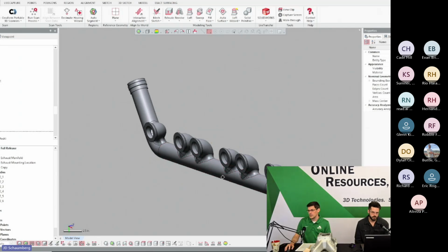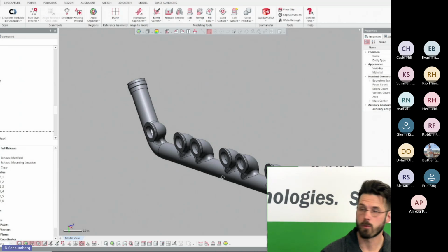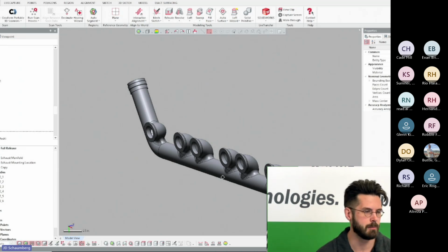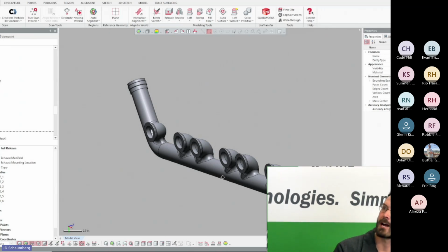A lot of times when we're doing the reverse engineering of the castings, people just ask us for a uniform wall thickness. If that's not the case, and there are some unique geometries on the inside surfaces of the part, the unfortunate reality in some cases is that the parts need to be sacrificed in order to collect those. Many scanning systems are all line of sight, so if there's any deep passageways that you can't collect, in some cases, if we can sacrifice the part, that's one of the options.